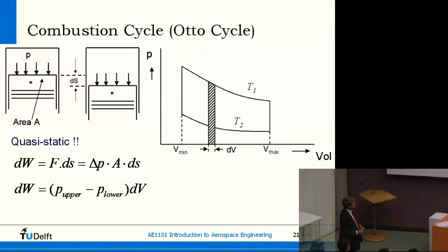So if we have a complete cycle where the temperature goes up and then it's compressed again, let's see, here's where the temperature goes up. So here's the burning, then we have a higher pressure, and then we increase the volume again, and then we lower the temperature again. Then we have to compress again, and this is the cycle, the 4 strokes of the engine.